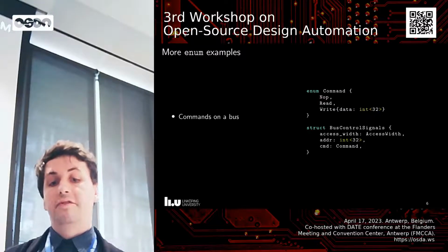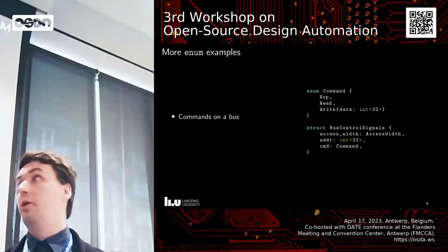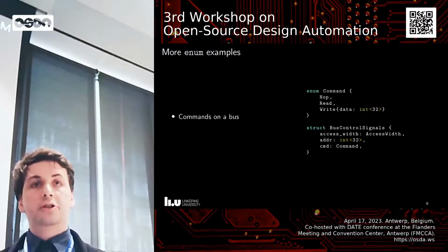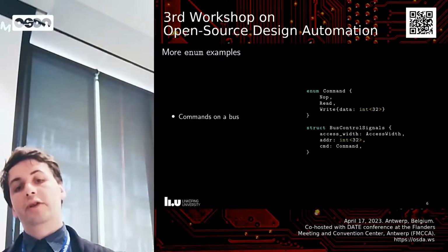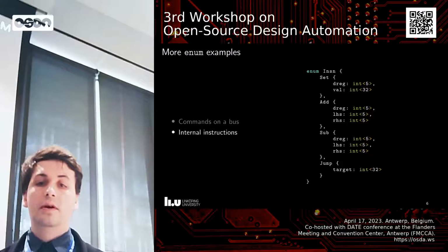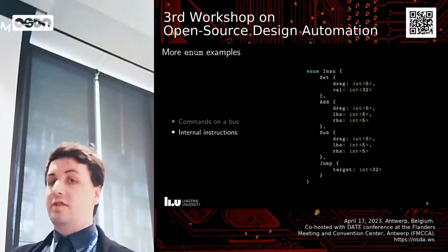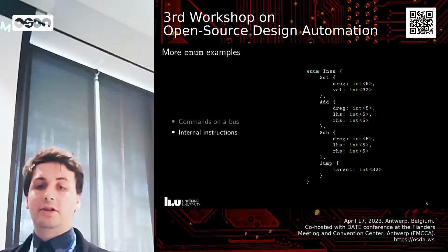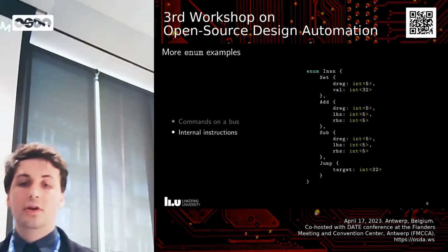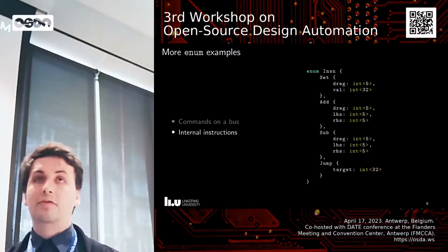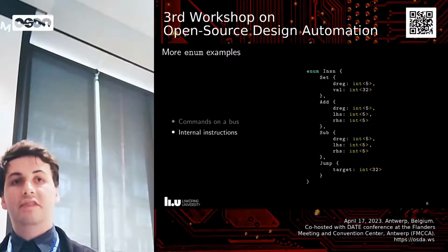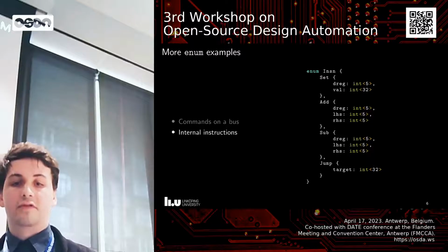This is very useful for a lot of other things as well. You could model commands on a bus. For example, if you have a memory, you could have no operation on the memory, you could have a read operation, or you could have a write operation, and you can bundle the data that it needs. You can model an instruction set. So you have a set instruction where you have a destination register and an immediate value. You have an add instruction where you have a destination register and two input registers. Or you can have a jump instruction, which is a target. And this will be encoded in a similar way. And it's very nice to match on these, and then you only get access to the fields of your instruction that you actually have a use for.